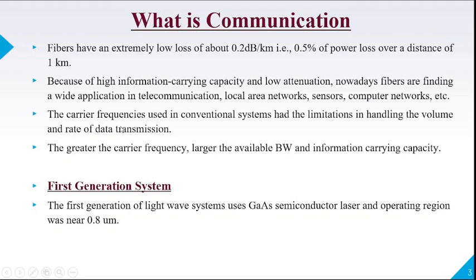The carrier frequencies used in conventional systems had limitations in handling the volume and rate of data transmission. The greater the carrier frequency, the larger the available bandwidth and information carrying capacity. As we know, as the bandwidth is high, information carrying capacity is high, and for the bandwidth to be higher, the carrier frequency should be greater. Then we'll see the generations of optical communication system one by one.